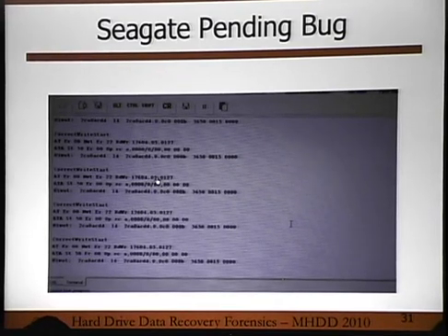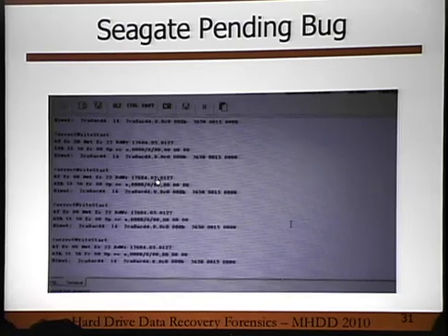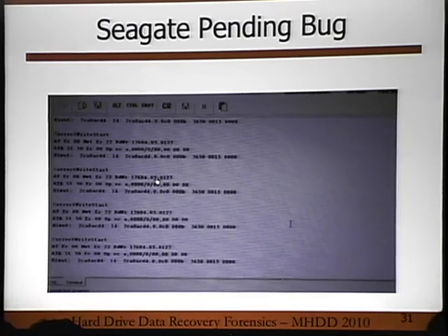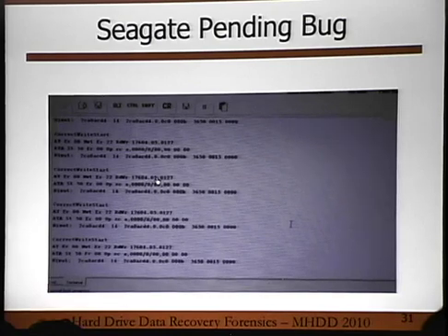What happens is the drive is trying to do wear leveling, and something went wrong in the firmware. So instead of constantly reading your data and giving it back to you, it's tying up the processor. The processor is trying to do this wear leveling process over and over and over again and will not be successful at it. It'll never end. And so you'll end up spending like two months trying to copy 750 gigs, if you're even able to do it in two months.